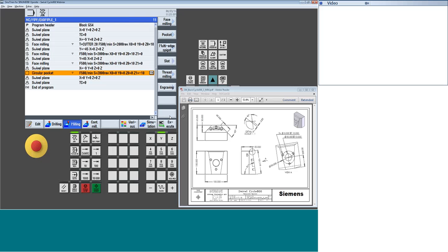Now, once I machine the pocket, I do want to come down here on this corner, rotate, and machine that 45. So this would be a case where I'd want to use the additive function because I have a 0 staged. I know this edge, right? So I can get to that corner. I can do an additional 45 degree of rotation relative to this 9 degree because I see my angle is based on this plane, not the top of my part.